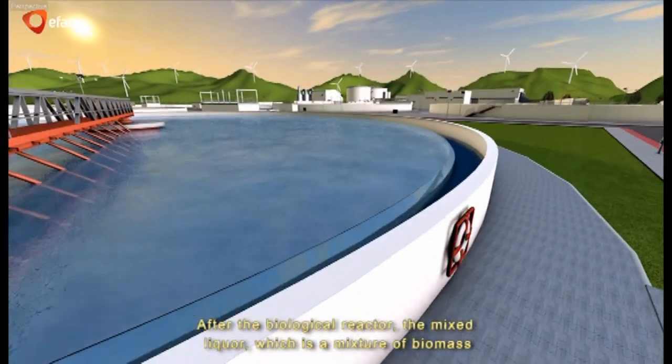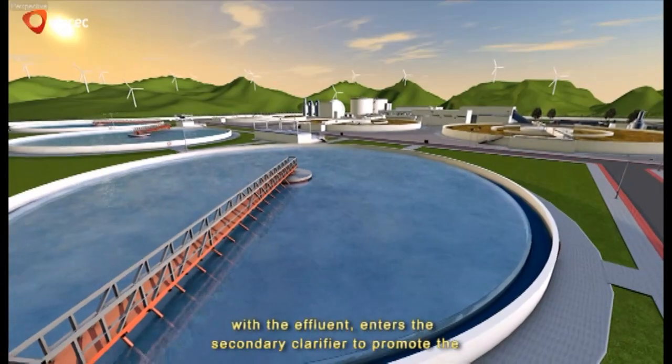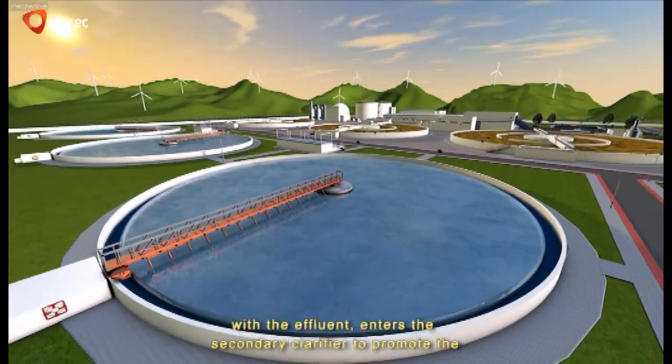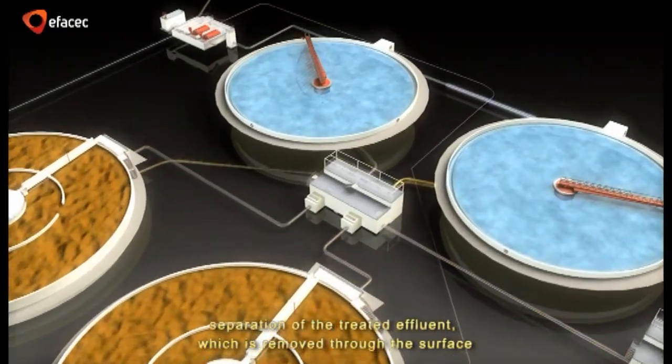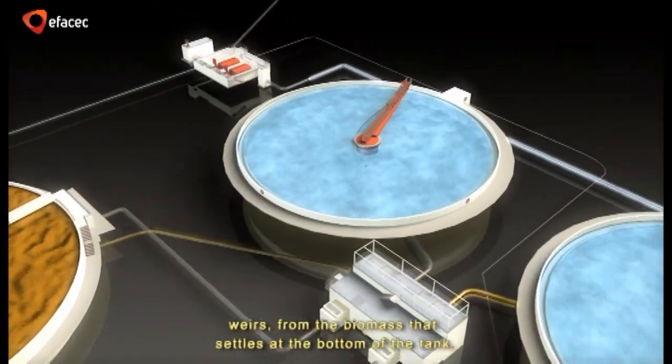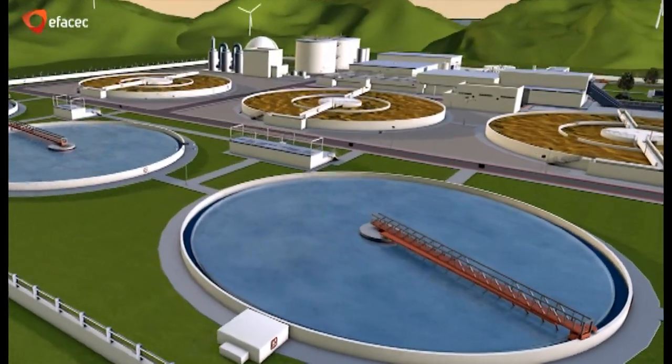After the biological reactor, the mixed liquor, which is a mixture of biomass with the effluent, enters the secondary clarifier to promote the separation of the treated effluent, which is removed through the surface weirs, from the biomass that settles at the bottom of the tank.